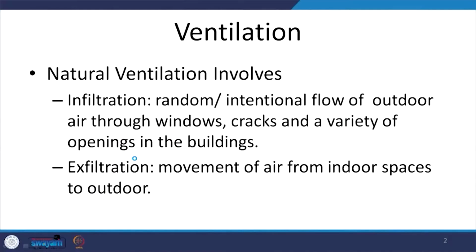Natural ventilation would involve infiltration, which is the bringing in of air unintentionally through windows or cracks in the openings of the buildings. And there is exfiltration, which is the movement of air from indoor spaces to outdoor spaces.